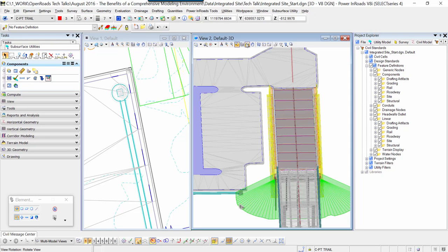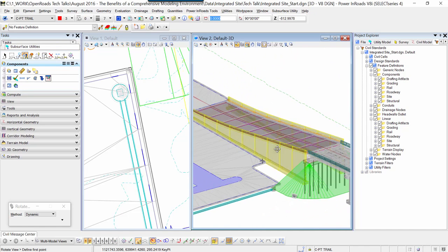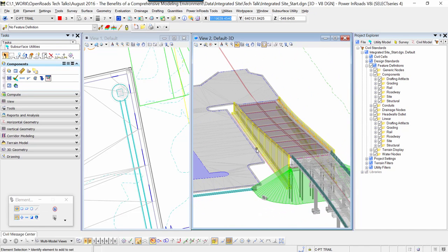Recognize that when we talk about modeling, and I will expand on this, and many of you may have already seen these things when it comes to OpenRoads tools and technology. The model is an engineered model. It's a model that contains your design intent, that understands that you make the decisions of how side slopes tie to one another. You make the decisions on how the slope of the pipe interacts with the inlet and so forth. Okay?